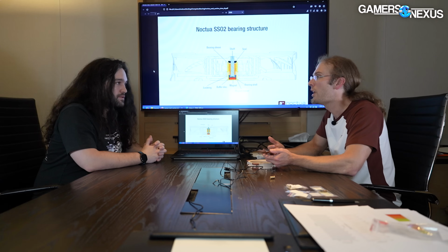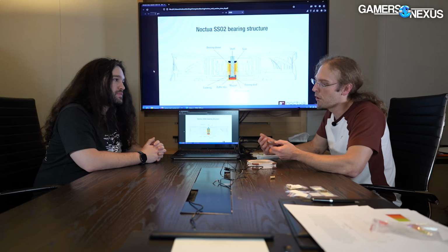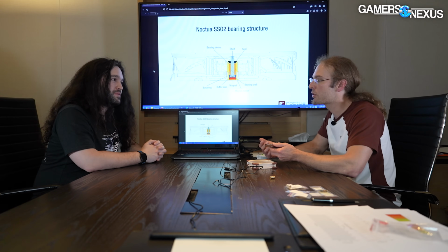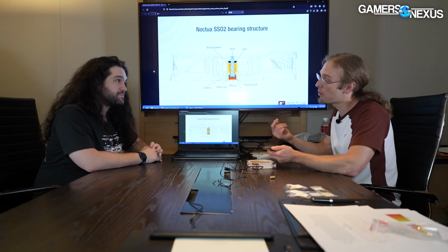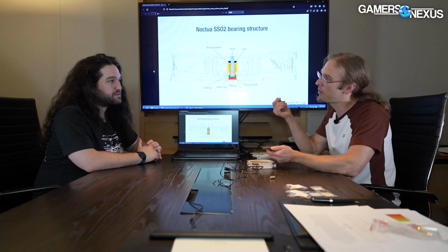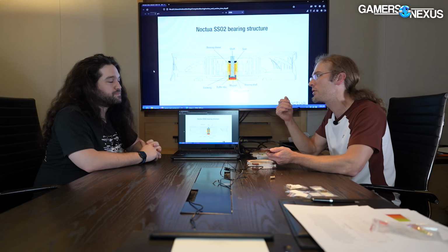The key advantage of the grooving is that you can use higher viscosity lubricants. So that's something you basically only need if you run higher temperatures. And that's another example for, I would ask the question, in what sense is a bearing better and what for? Because, okay, that makes it better for higher temperatures, but the higher viscosity lubricants increase the time to no contact between the shaft and the bearing sleeve. So that time until that pressure field builds up is longer the higher the viscosity of the lubricant.